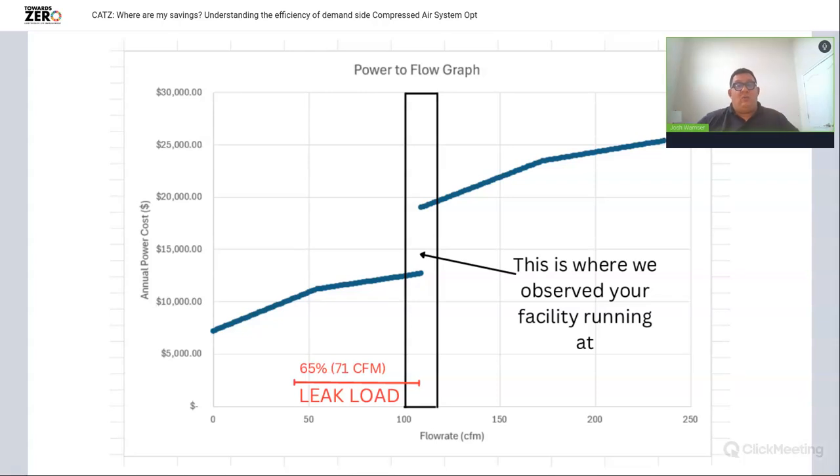When the demand profile is higher than the supply's capabilities, first of all storage is used up, pressure starts dropping, and now the compressors are constantly loaded and pressure is changing based on changes in demand. So those two things can fight back and forth and completely change the way the compressors operate, everything from power to maintenance to whatever else.